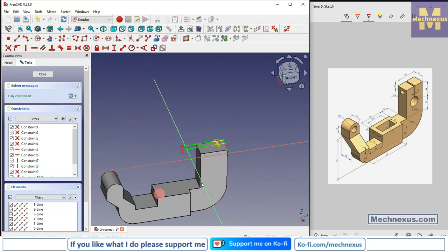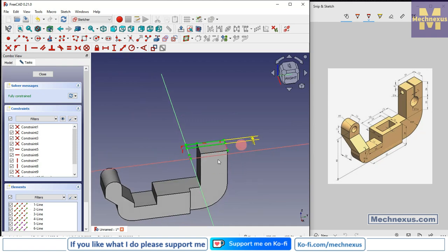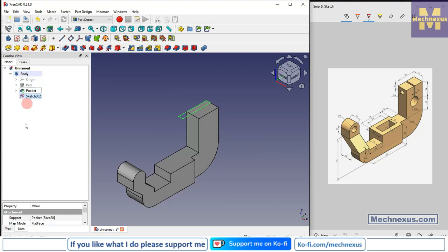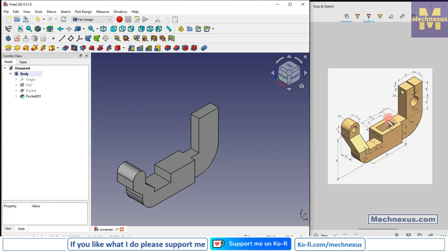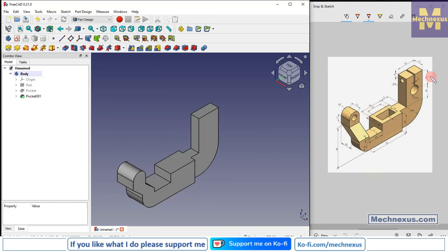36 is actually from this edge, but we have already made a cut on one side, so we will add the collinear relation. Click on close, click on cut, and from here say through all. So now we have made these two cuts. One is on the left hand side, the other is on the right hand side, and now we will create this cut.